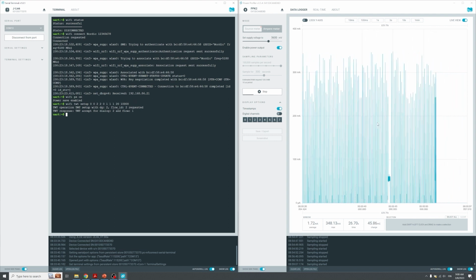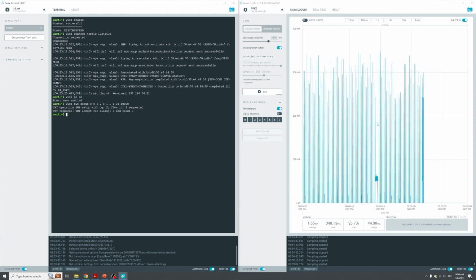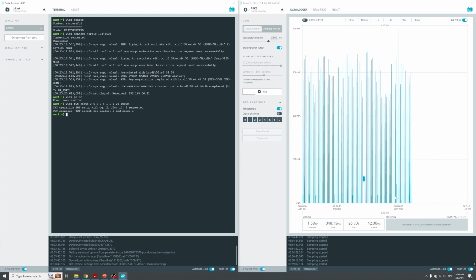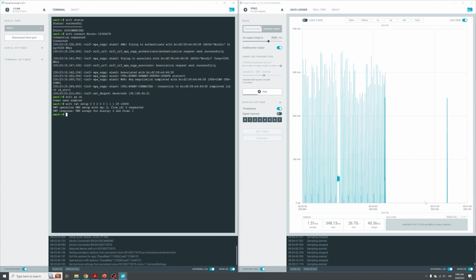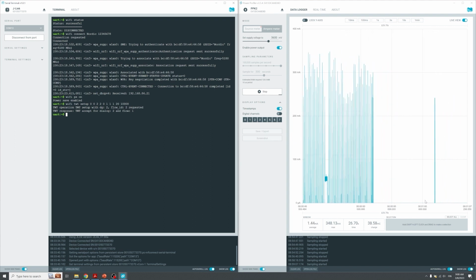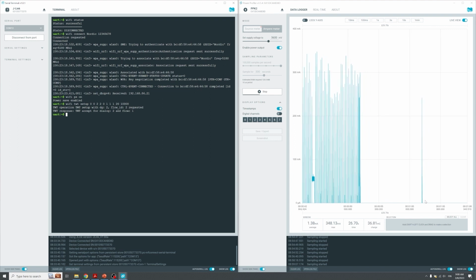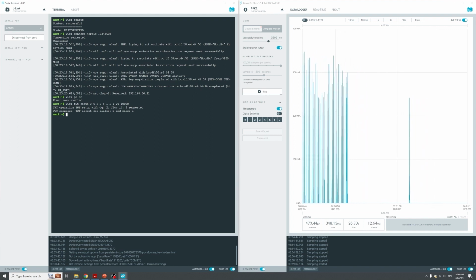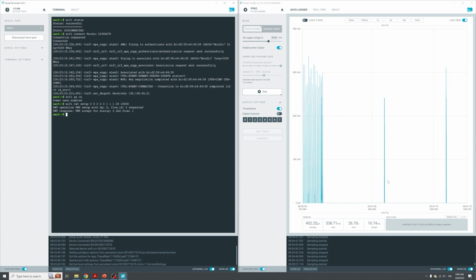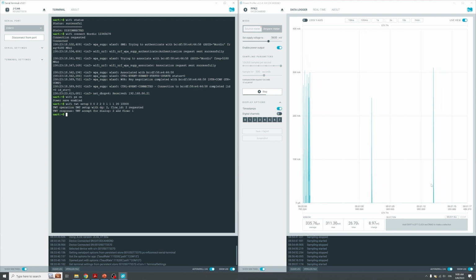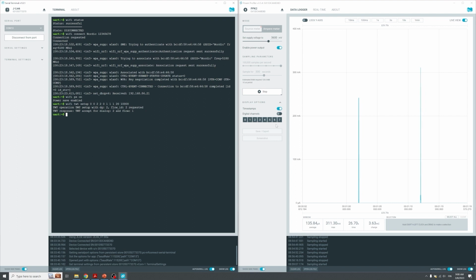Okay, so it seems that our device can spend a lot more time in low power mode, which is exactly what we were looking for. And now the device and the access point are interacting still at regular intervals, but at 10-second intervals. So that was the request that the station made to the access point. So we had the first one over here, and then the second one, and let's see if we can wait and capture the third one as well before we... okay, there we go.